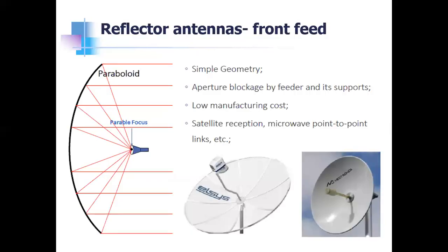An ideal feed for a paraboloid reflector is supposed to be at the focus with a radiation pattern that has no phase variation, and the feed should be such that it produces the desired aperture illumination at the reflecting surface. The directivity also should be sufficient to allow all of the radiated field to be intercepted by the aperture without any spillover, right?